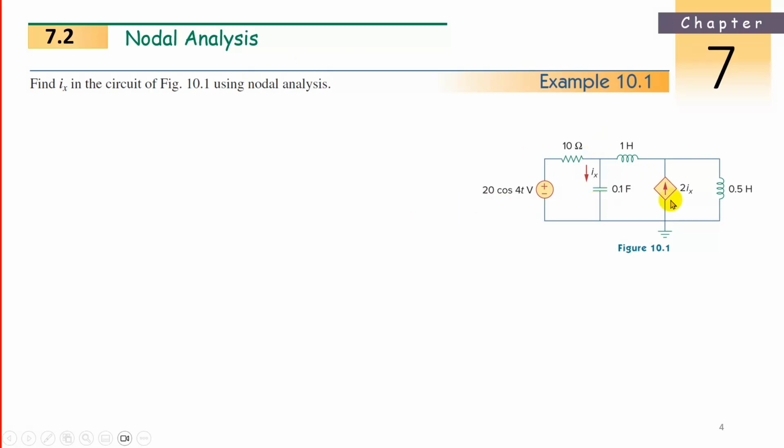Now, see the circuit here. In the circuit, what are the elements given? The same technique we have to use, node analysis, what we studied previously. First we have to see how many branches, how many elements, then how many nodes. Okay, see here, how many nodes do we have here? 1, 2, and this is the reference node, right? 2 nodes we have, and with the reference node, 2 plus 1, total 3 are there. But in node analysis, 1 is the reference node, that is node 0, it is already given. So we need 2 node equations.